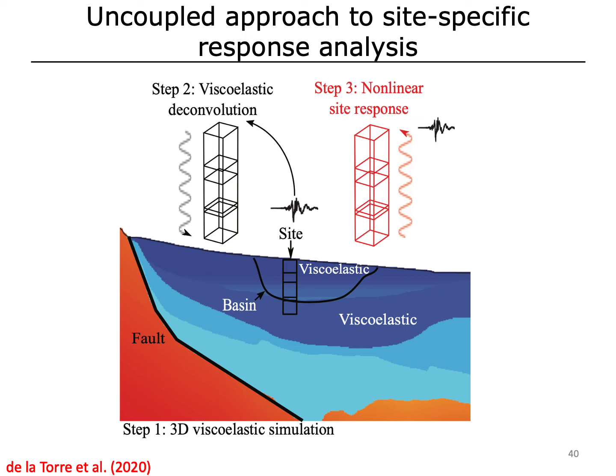The main challenge being that these ground motion simulations are performed on the order of hundreds of kilometers in regional scale, and often with a spatial discretization of tens or hundreds of meters, whereas often in geotechnical site response analysis, that spatial discretization, at least vertically, can be on the order of 1 meter or so. So typically we can't capture the near surface soil properties with the resolution in the ground motion simulations themselves.